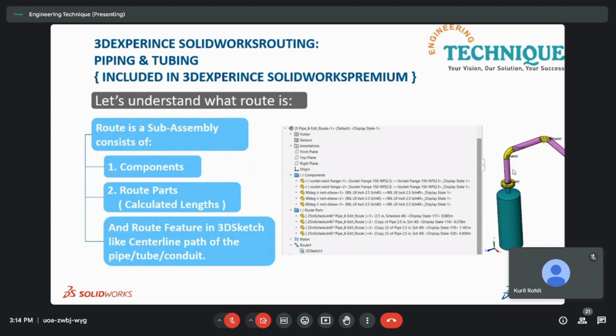Thirdly, and the most important thing again I'm going to say is 3D sketch, because if you misbehave with the sketch, the sketch is going to misbehave with you. Whilst creating a 3D sketch, you have to make sure to add a certain relation, add a certain length, so that you can utilize and you can get what output you need.